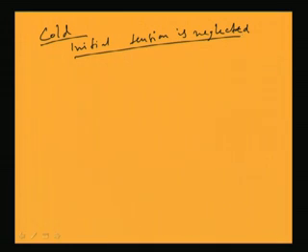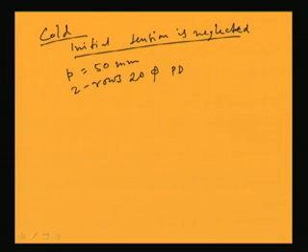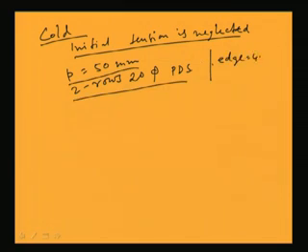Similarly, we are considering the pitch distance as 5 centimeter, that is 50 millimeter center to center, and 2 rows of 25 power driven shop rivets. These are the assumptions we have considered. Earlier, like in earlier cases, these two we are considering, and the edge distance we are also considering as 40 mm, right. So now we can find out the value of n.